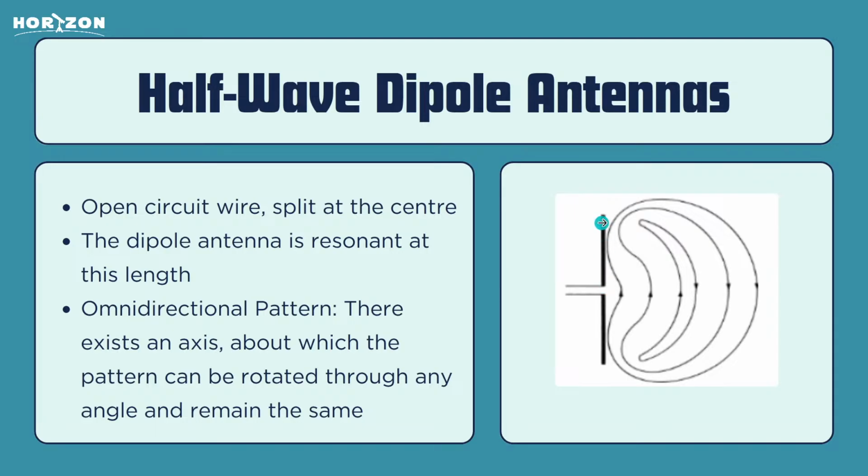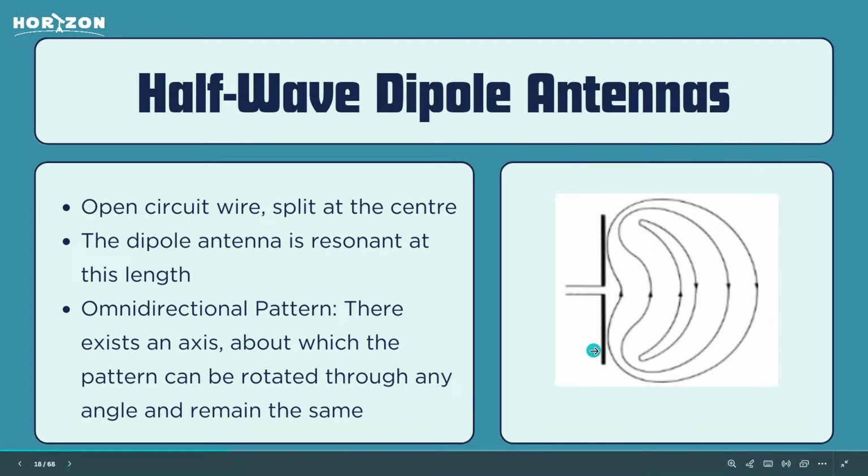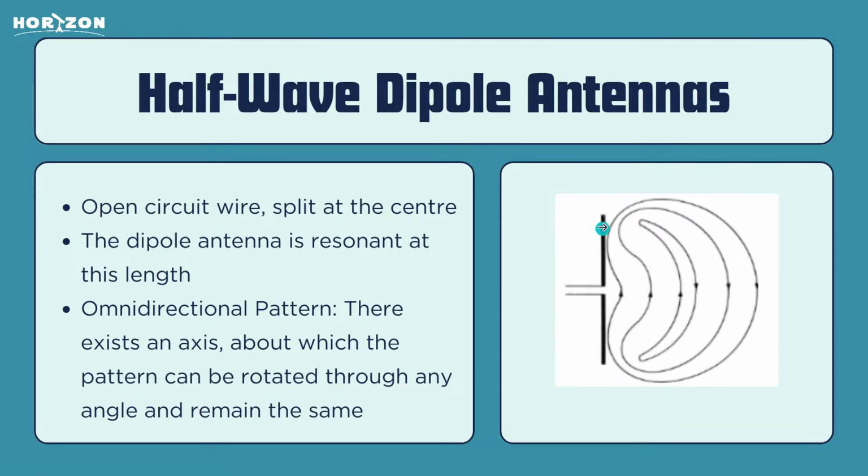This length of the antenna is lambda by 2. So we'll go up, travel a lambda by 2. Sorry, it's actually lambda by 4 since the total length is half a wavelength. So half of the antenna itself is lambda by 4. So once the current travels from here to here, its phase has changed by lambda by 4 into 2 pi, which is pi by 2. And there is nowhere else for the current to go after this.